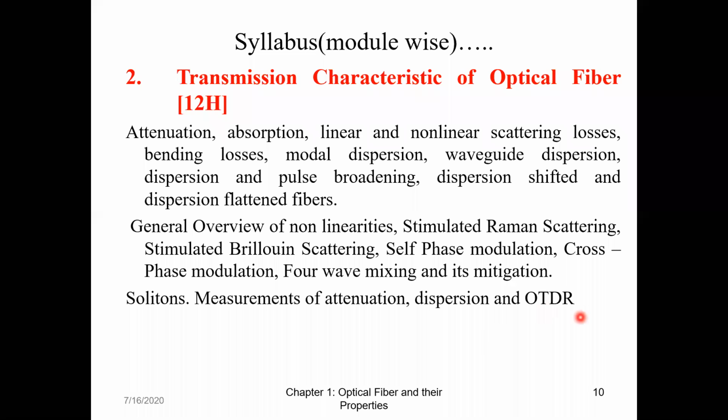Sometimes the fiber bends due to some reason, it might not be cut. So then we come to know, okay, around 20 kilometers, there is some problem with that particular fiber. So from my office, we travel exactly 20 kilometers and then we dig up and do all those things. So OTDR is an instrument which gives you the reading or the measurement of all the losses that you